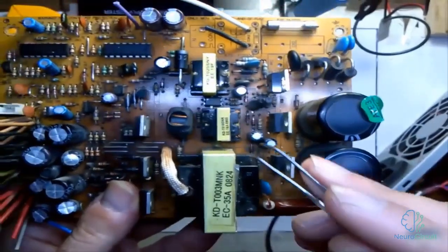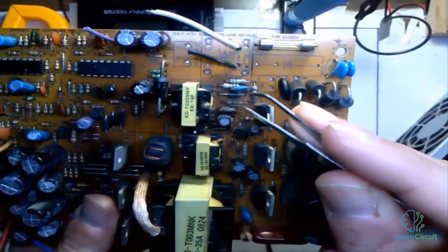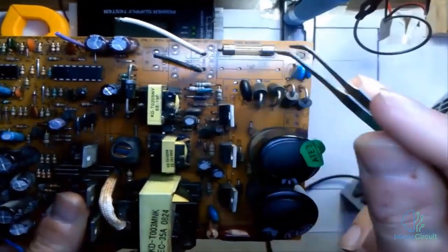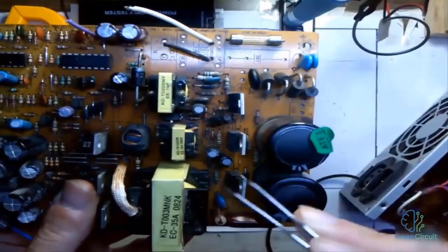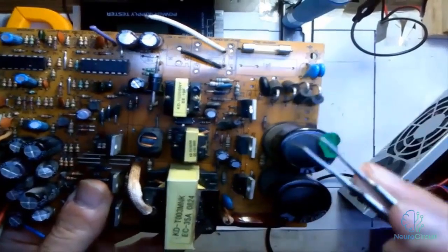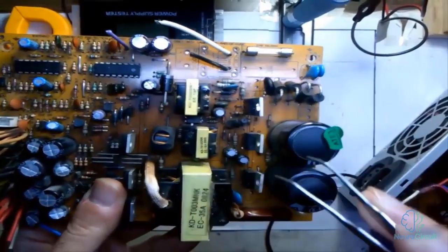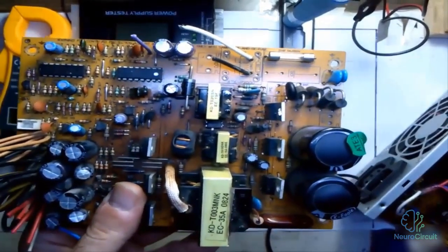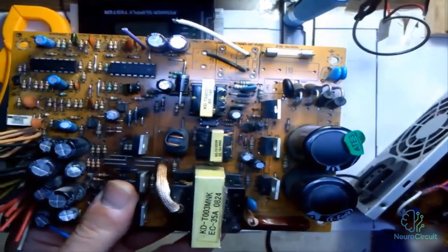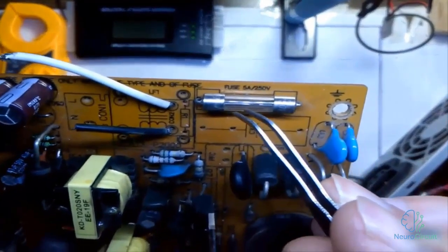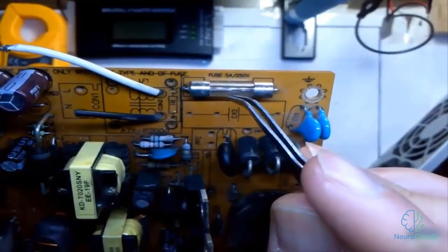So if you see a power supply that is not turning on, for example, it won't power up, the first thing you should do is test the primary circuit. Here, because at first we need to see whether the primary circuit is actually functional and can conduct electricity properly. If we are sure that the primary circuit is healthy, then we should move on to the next circuit. So the path you need to follow starts with the fuse. When a power supply doesn't turn on, you need to check whether the fuse is intact.